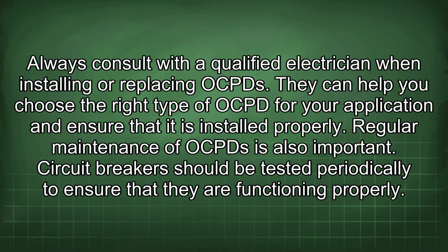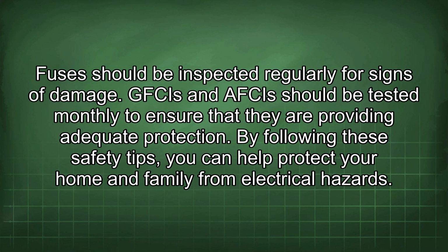Regular maintenance of OCPDs is also important. Circuit breakers should be tested periodically to ensure that they are functioning properly. Fuses should be inspected regularly for signs of damage. GFCIs and AFCIs should be tested monthly to ensure that they are providing adequate protection. By following these safety tips, you can help protect your home and family from electrical hazards.